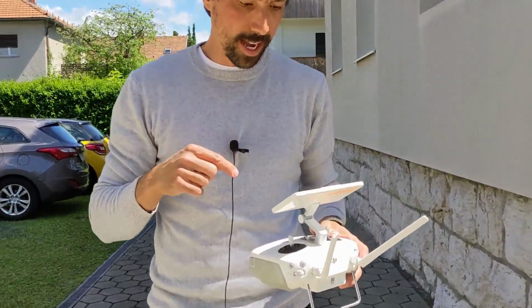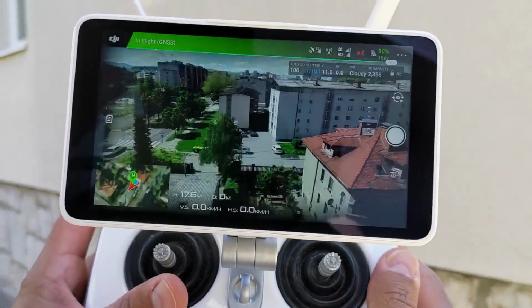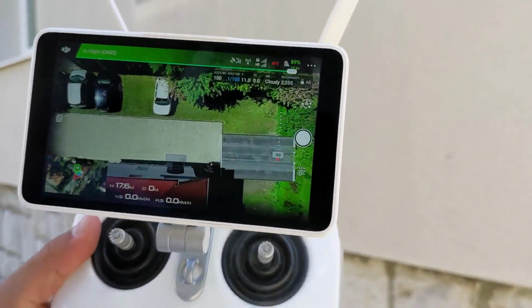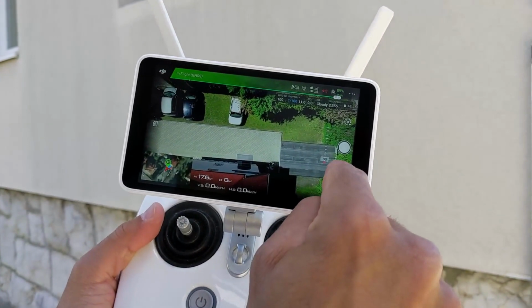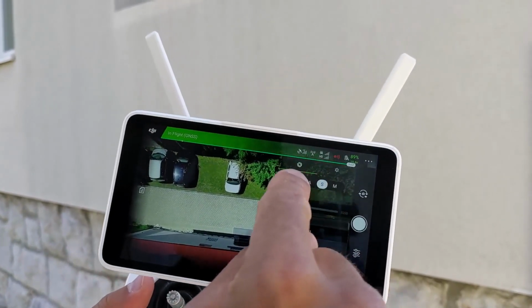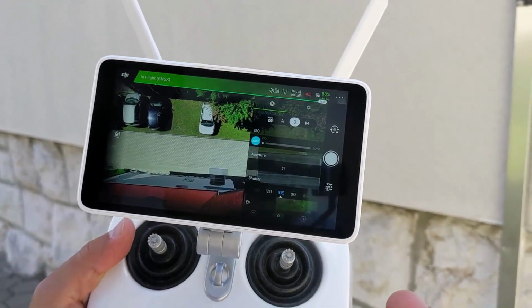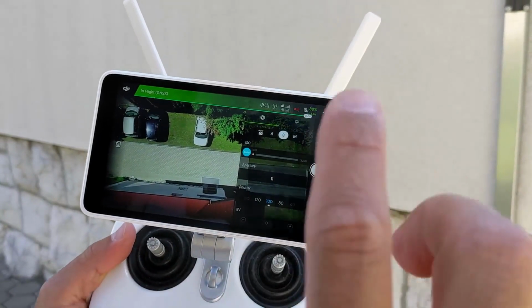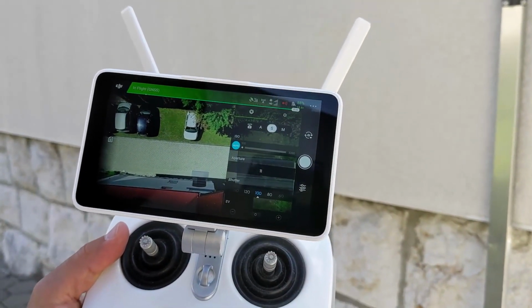Now we can go and see the screen, what I can actually see. I will turn the gimbal down to have the camera view perpendicular down, because I will map in these settings, and I will go to camera settings here and select shutter priority mode, because with shutter priority you fix the shutter time, and then the aperture is automatically recalculated, and also the ISO value is recalculated.